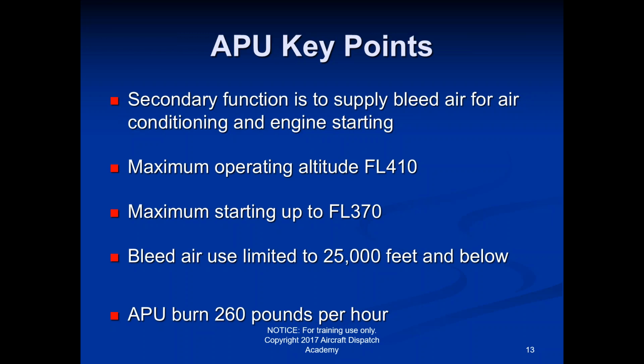They can send it out to the right engine, and it'll start making that bleed air run through whatever engine they're wanting to start. And as the air gets in there, they can turn on their starter, which will ignite the fuel and the air all together, and then it starts that whole process of getting the engine going. An engine startup takes roughly 30 to 45 seconds, probably, total.